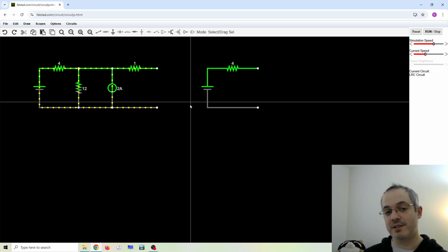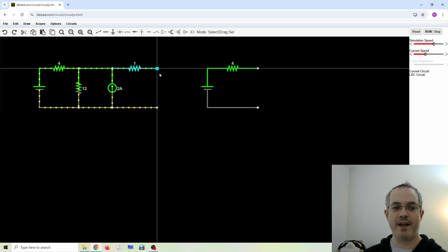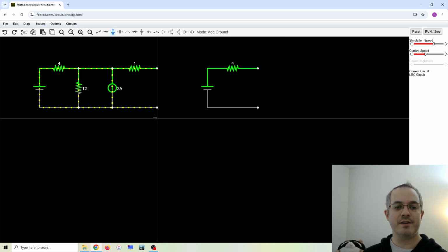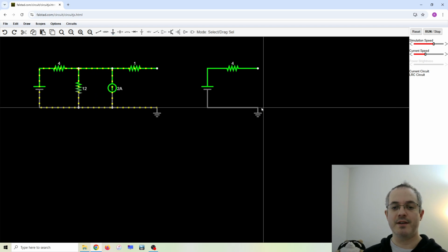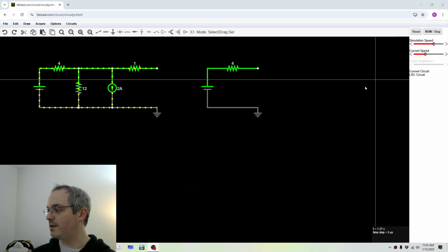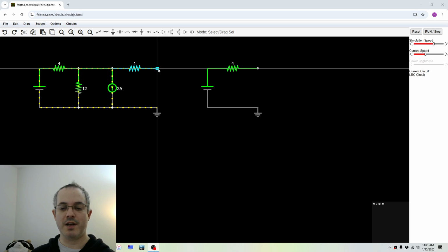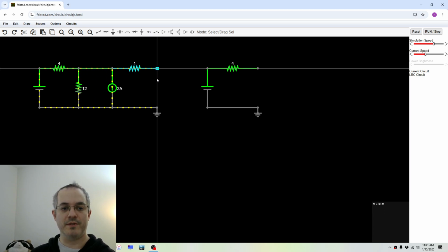You should be able to check the voltage. The best way to check the voltage is going to be to just look at the voltage difference between the bottom and top wires. Sometimes when you do two circuits here, you're going to need to throw in a ground. So just go ahead and make one of them be ground. That makes it 0 volts. That makes the one that you connect the ground to 0. The one on the top says 30.